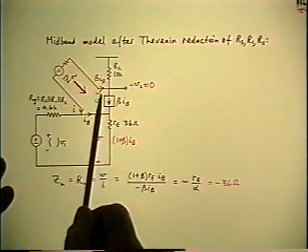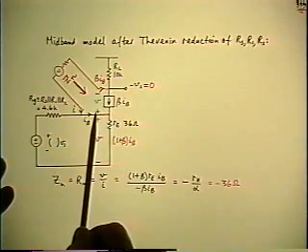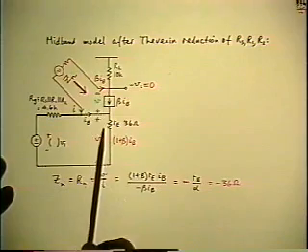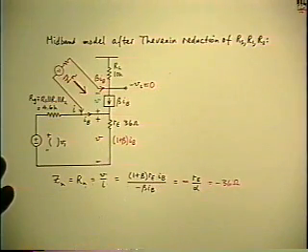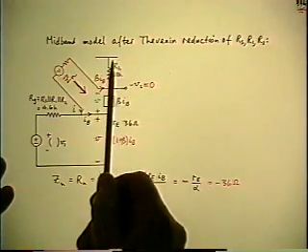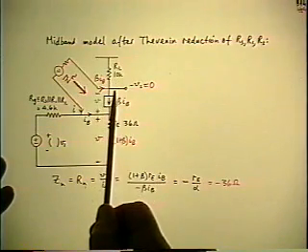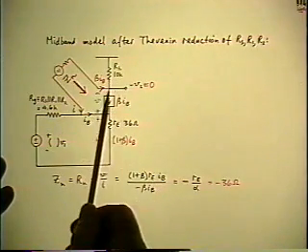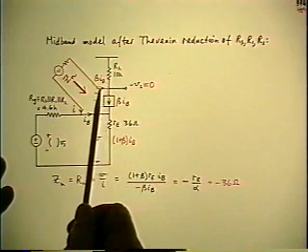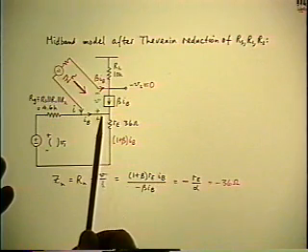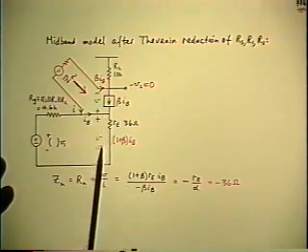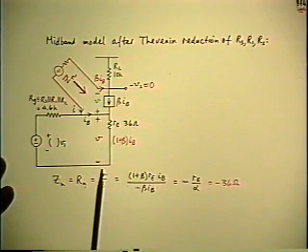The second step is I want to know what the V is. The green V equals the red V, again because there is a null across the output. So this is AC ground at the output. If I step up by a green V from AC ground to the base, then I have to step down by the red V the same amount to get back to AC ground again.